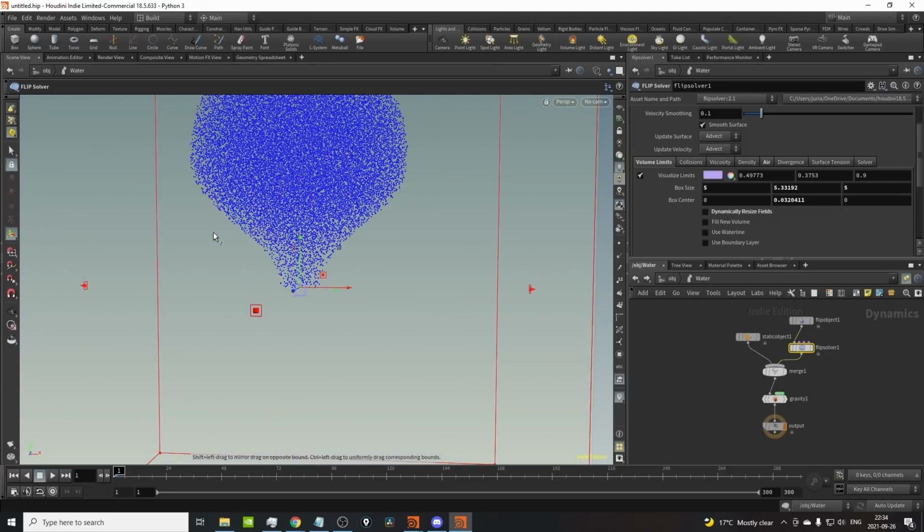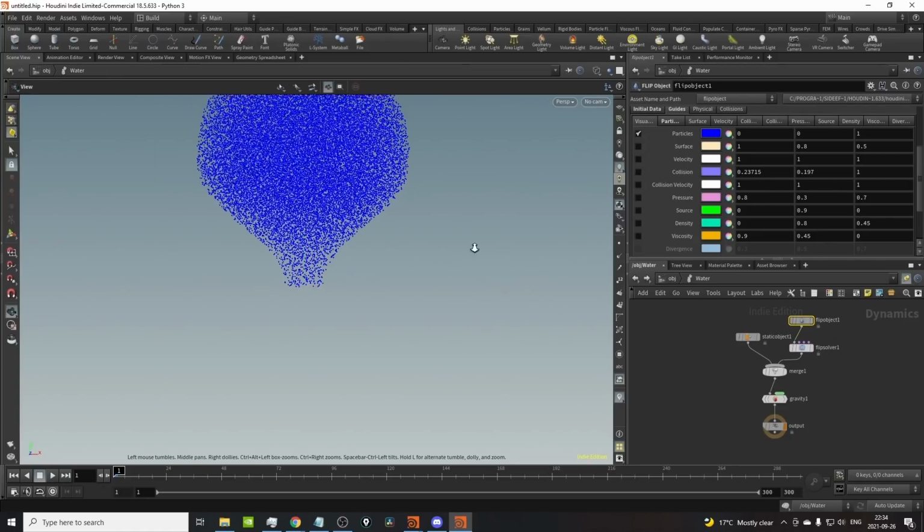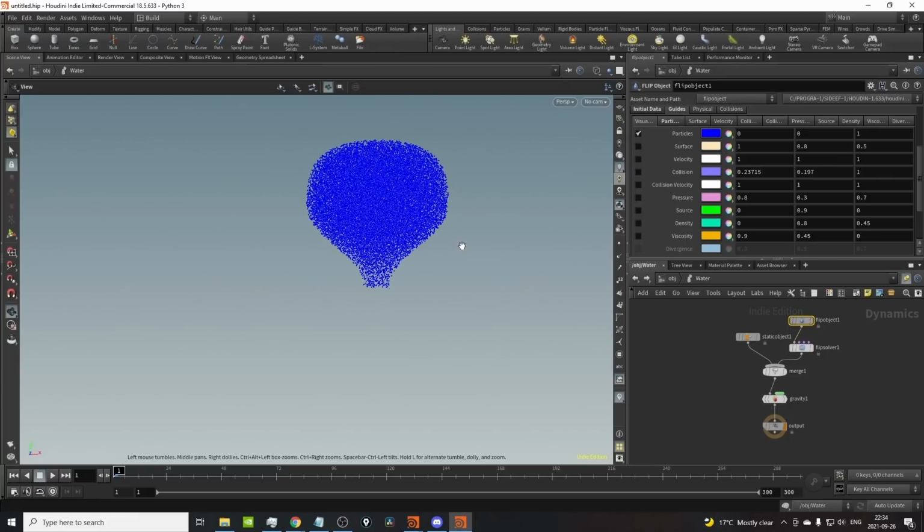Also, we can't really do this with narrowband as well. That's really the main limitation of it. You can't run narrowband on it, and you need to turn off dynamic resizing. You can get lucky and it will do something, it just won't be as accurate as it will be if you turn that off.